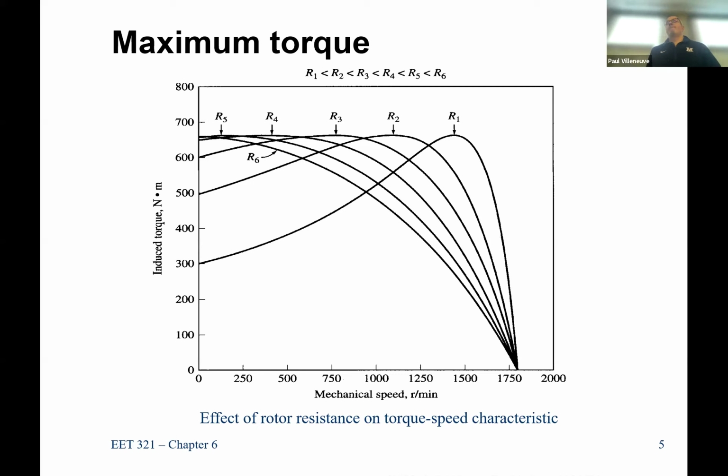Depending on how you drive, it's possible, but I would imagine most of the time you're using a three-phase induction motor. It's a solid connection. There's a keyway that you're just bolted together, and that's typically what you've seen, because a belt, if you're putting out 500 horsepower, all that power going through a leather or rubber belt, doesn't last very long, right? So when does maximum efficiency for an induction motor occur?